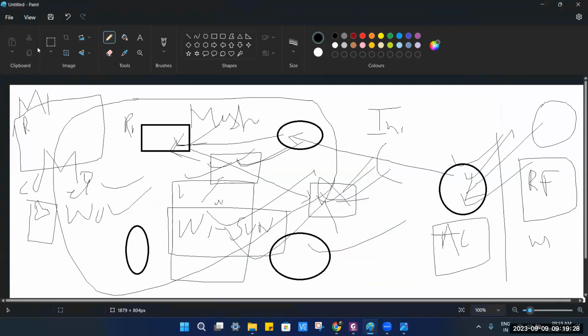If we need to run a full-fledged system, we have to use Cortex A, because for running Linux and these things you need virtual memory, and for that you need a memory management unit. In ARM Cortex M, we don't have that at the moment. We only use MPU because MMU will create an overhead, and overhead sometimes is not good for a real-time system. So if you are building a real-time system, you will be using an MCU rather than any SoCs.